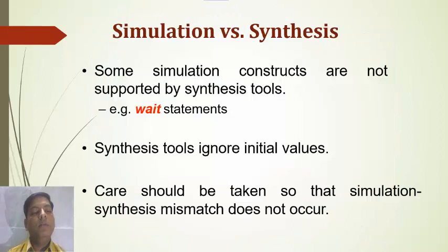Then we are discussing simulation versus synthesis. Some simulation constructs are not supported by synthesis tools, for example, the wait statement. Synthesis tools ignore initial values. Care should be taken so that simulation and synthesis mismatch does not occur.